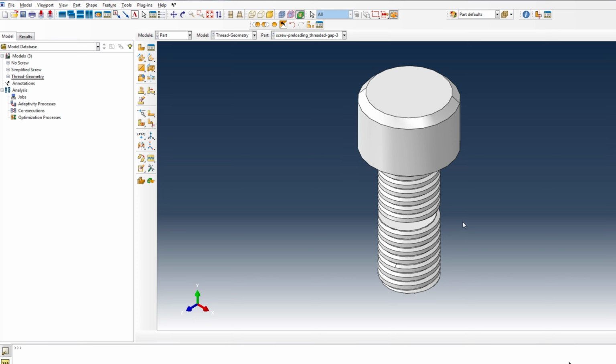Normally we could run a first static or quasi-static analysis using Abaqus Standard, and after solving the bolt preloading time step, we could use the results as a pre-stressed condition for a subsequent step in the Explicit solver.